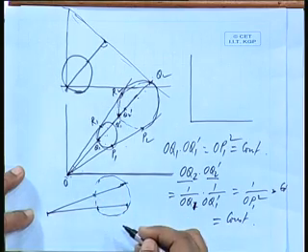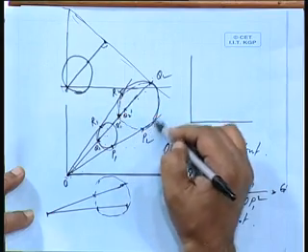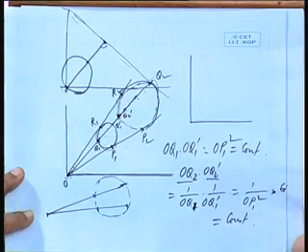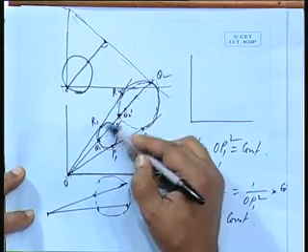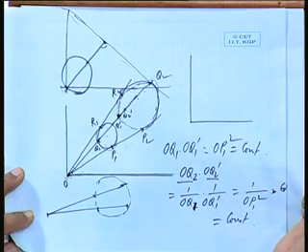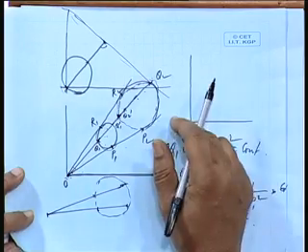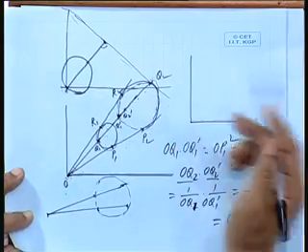Okay. So, all these points will lie on a circle, they are all inverses of these. So, the inverse of a circle when the origin is outside that circle is also another circle. We will make use of this relationship for the computation of currents, the locus of currents in different situations.